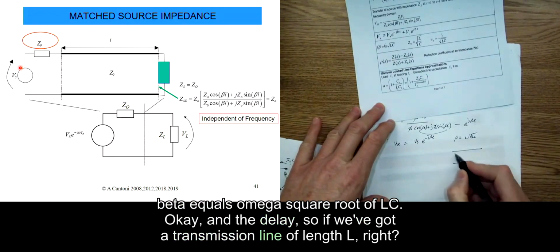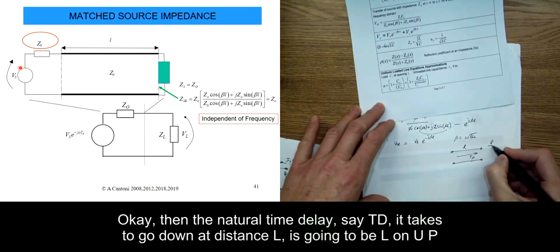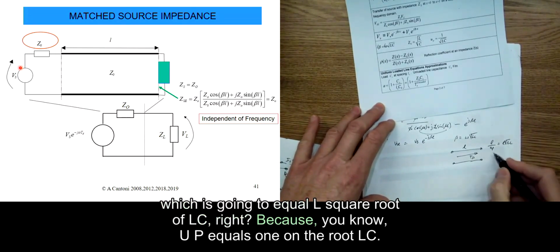Now the delay. If we've got a transmission line of length L, then the actual time delay, say TD, it takes to go down that distance L is going to be L on UP, which equals L square root of LC, because UP equals 1 on the root LC.